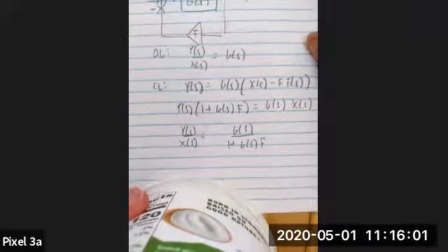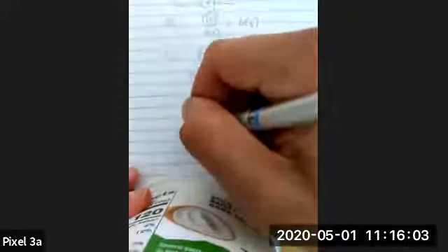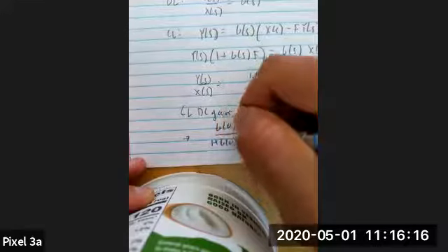So in this case, if we wanted to find the closed loop DC gain, we'll see that it occurs when s is equal to 0. So in this case, the DC gain is going to be g of 0 over 1 plus g of 0 times f.